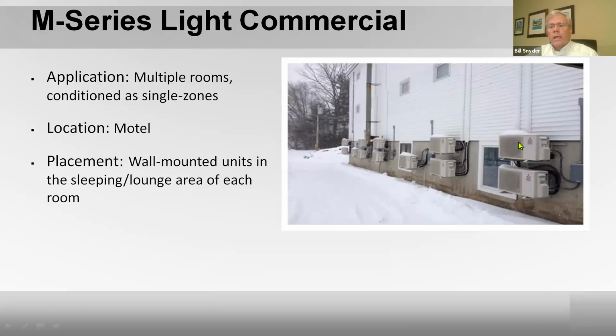If this was a heat pump system, and it went into defrost, this is open to the bottom unit here, and it would probably drop water and freeze up. This bottom unit would become a ball of ice.